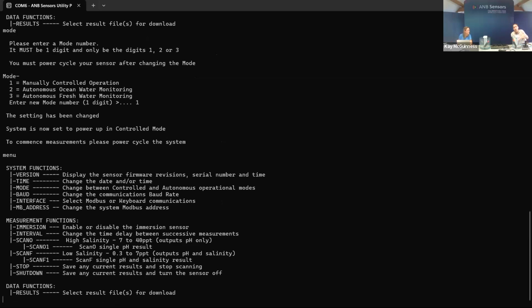Yeah, so this is just all around your data rate speed from the sensor to your device. We go anything from 9600 to 115200. From a factory setting, the baud rate is set at 57,600, as Kay showed you earlier. When we booted up utils, it found 57,600, but this is completely user configurable depending on your own integration system. And we have customers using anything from 9,600 up to 115,200. Perfect. So the next function is interface.